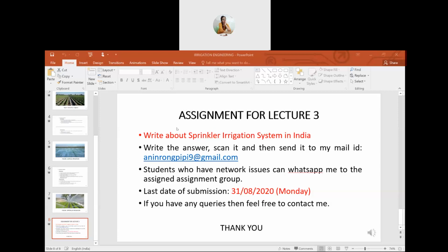Cutback irrigation is difficult to manage because as you remove the siphon tubes, you need to start new rows. Remember, you have to use all of the water coming into your supply canal or you will overtop the canal. An easier alternative is to put 2 tubes in every other row of your set. When the water is 2/3 of the way down the field, you move the double tubes to the dry row. When the water is 2/3 of the way down the row, you move 1 tube back to your original row.